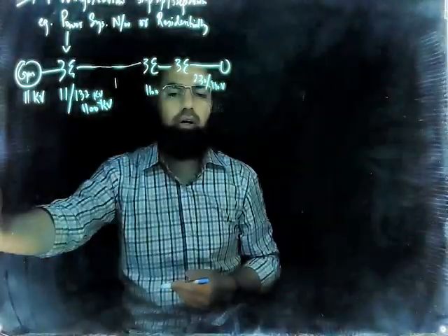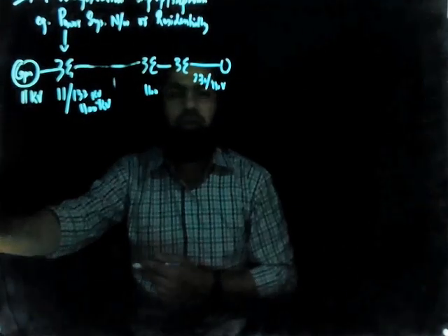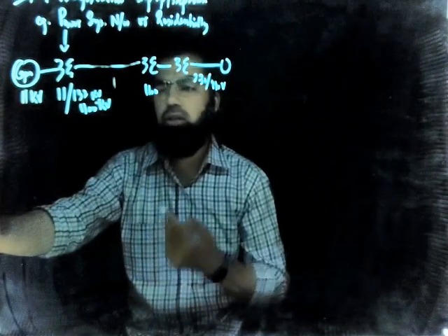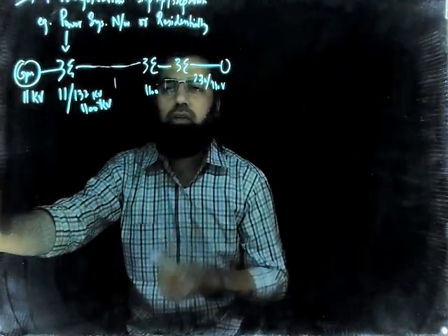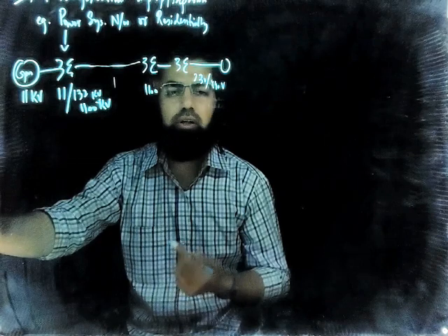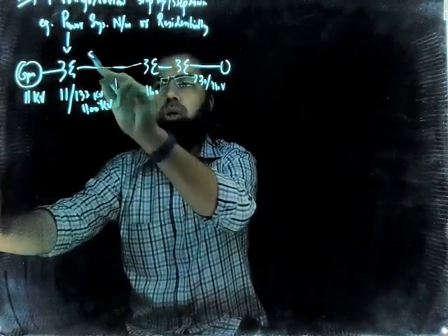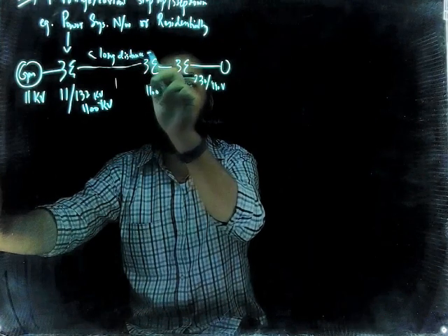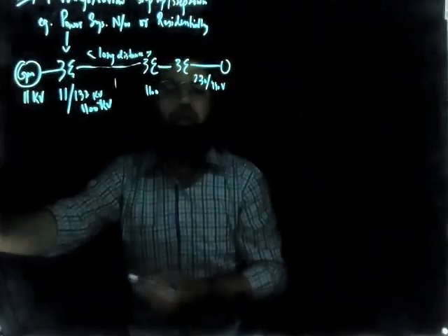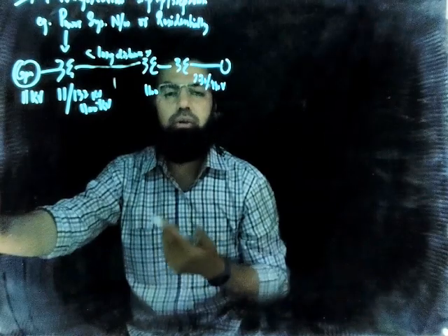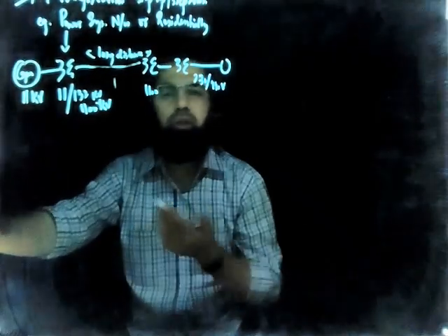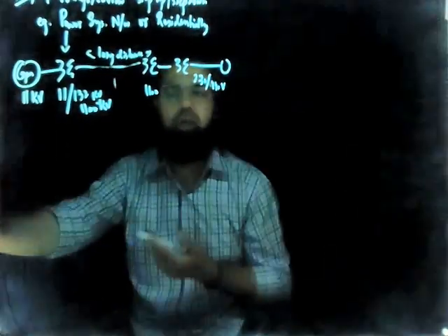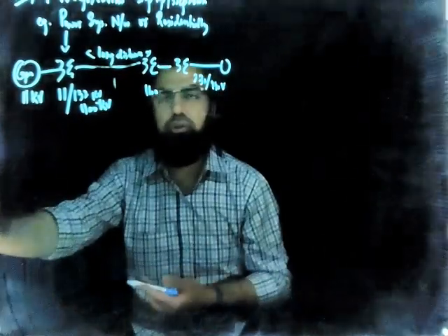So this is what we do in case of power system networks. The reason for stepping up the voltage is to transmit the voltage over long distances. By stepping up the voltage, the current steps down, I square R losses are reduced, and we can transmit the power over long range, over thousands of kilometers.